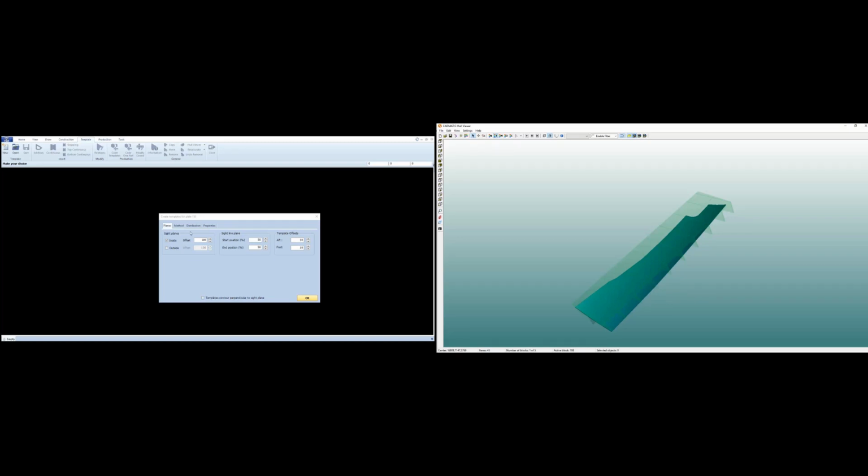So the side plane. You can have two side planes. If you choose to have the outside side plane, then the system will create templates on both sides of the shell plate. I will click it here so that you see. Now we have two side planes, and you also see a preview of templates on the other side as well. But I do not want to create templates on the other side for now, so I will uncheck this again.